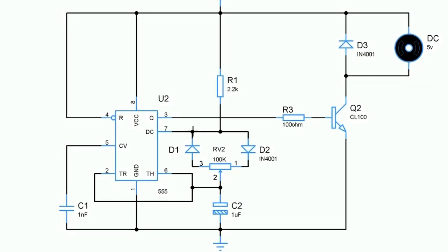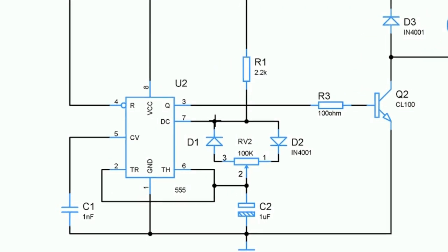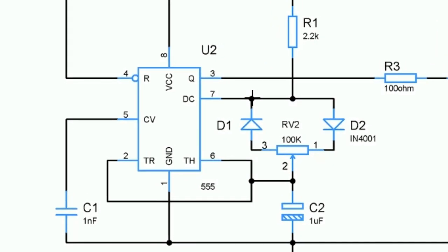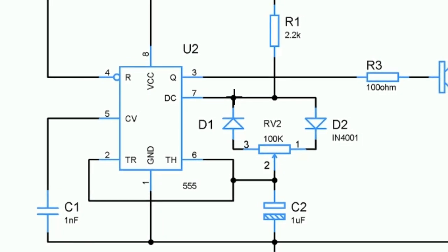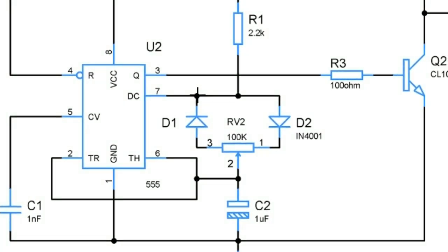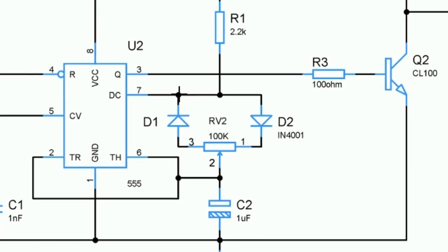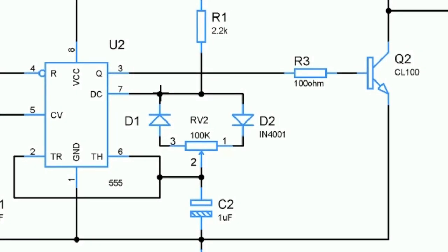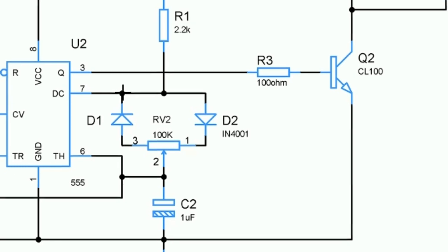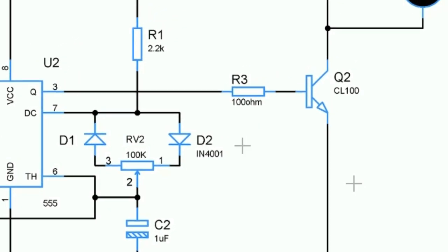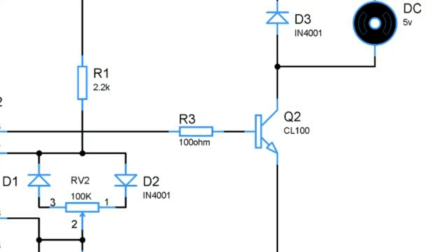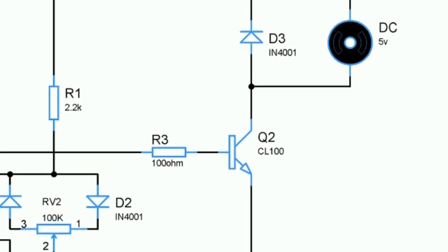Let's get into the quick summary of this circuit. This circuit uses a modified astable multivibrator using IC555. When the capacitor charges, the output of IC555 will go high, and it goes low when the capacitor discharges. To generate a PWM pulse using this modified astable multivibrator circuit, the charging and discharging paths of the capacitor should be different and should possess different resistance. The 555 timer IC cannot handle high current to drive a motor by itself. So in order to do that, we are using a transistor as a switch to drive the motor, and it serves as a motor driver.